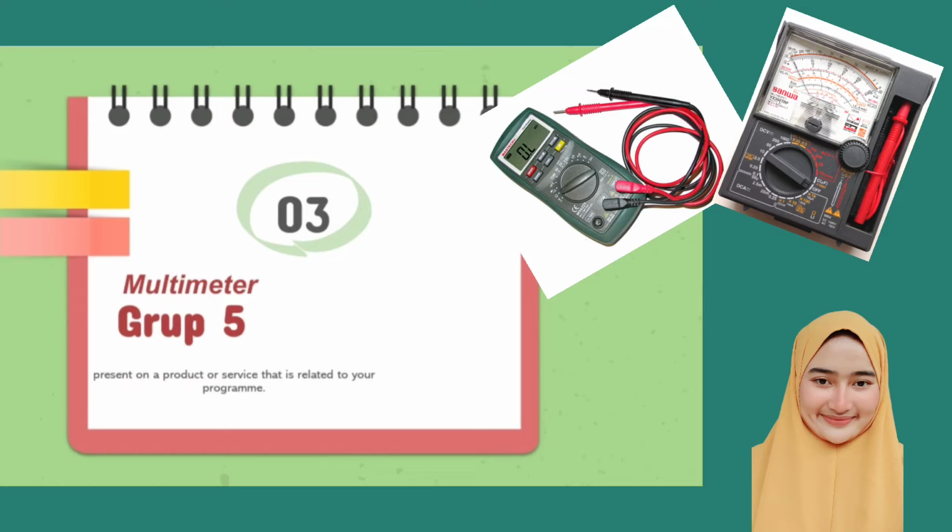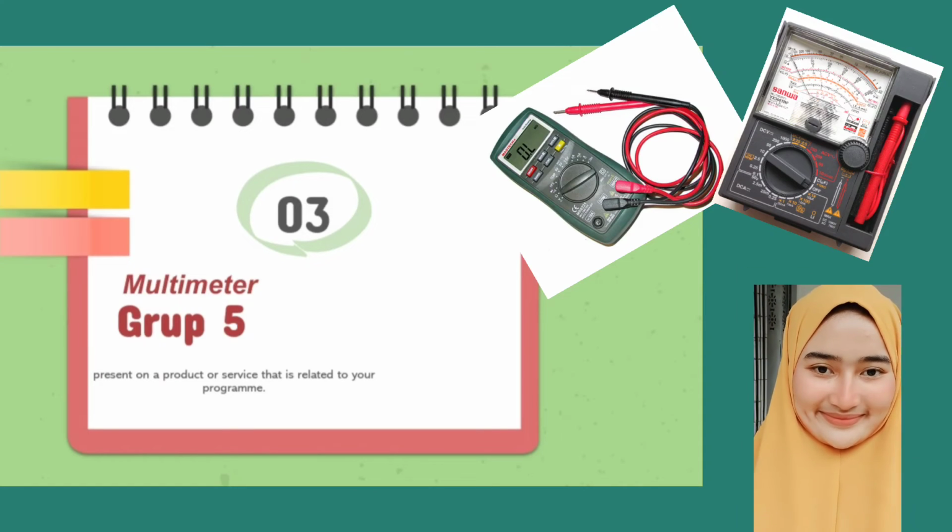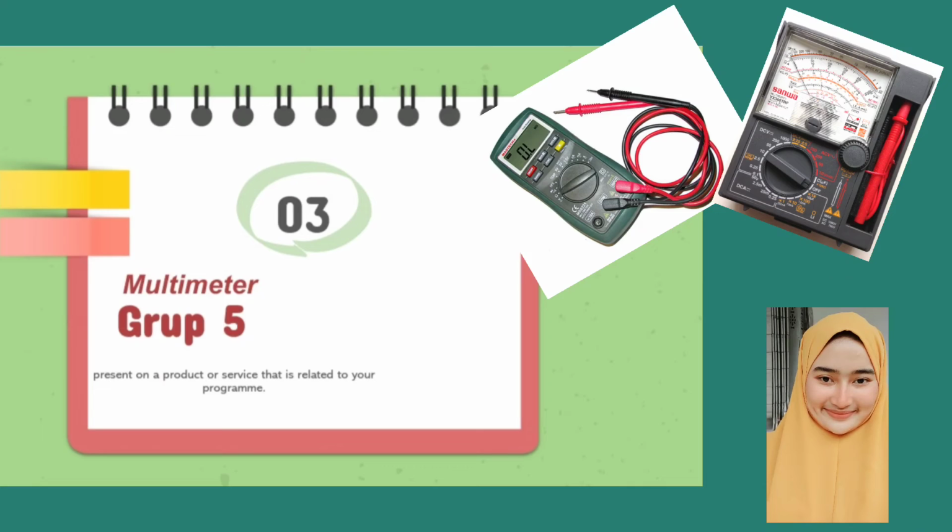Okay. Function of the multimeter. A multimeter is a multifunction and versatile measuring instrument. In general, a multimeter can measure DC current, DC voltage, AC voltage, resistance, and audio level, and so on. It can also measure current, capacitance, inductance, and some semiconductor parameters. The multimeter consists of the main parts: the meter head, the measuring circuit, and the exchange switch.